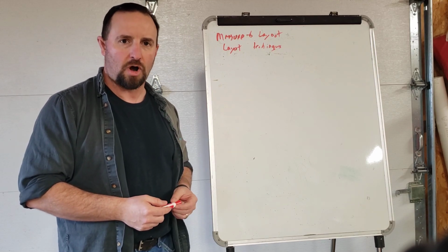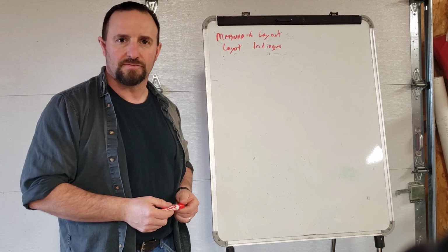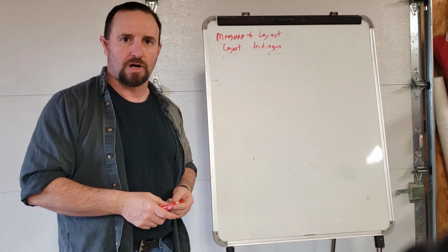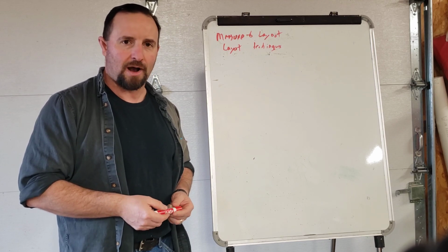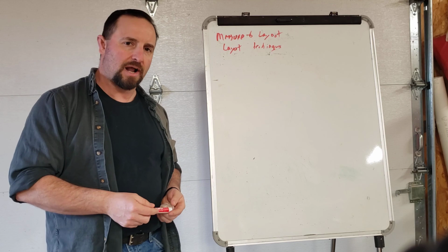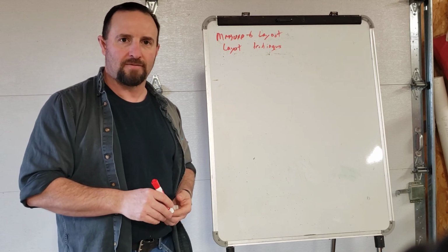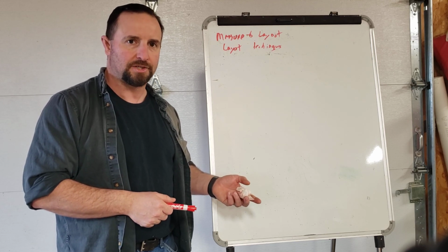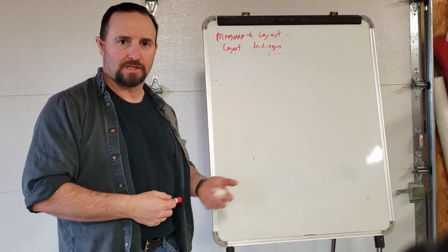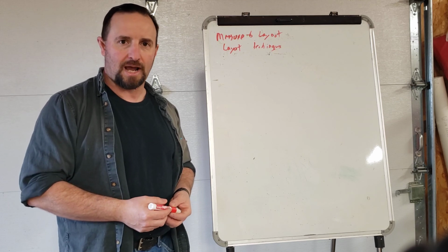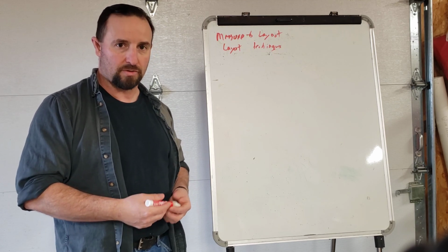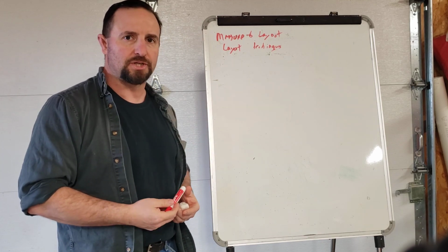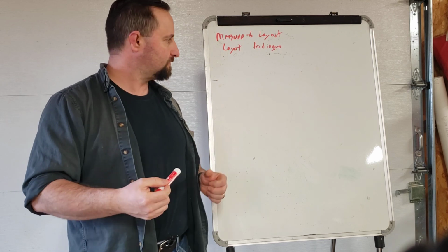That pillar was off, we figured, about 3 inches from where it was on the drawing. Close enough for structural work, not close enough for layout work. So when you get out in the real world, double check that everything is exactly where it's supposed to be, because remember, we've got tolerances we have to take into consideration. Our tolerance is the difference between acceptable and perfect, and if we're dealing with really big projects, that tolerance can be quite big. So make sure you're taking that into account.